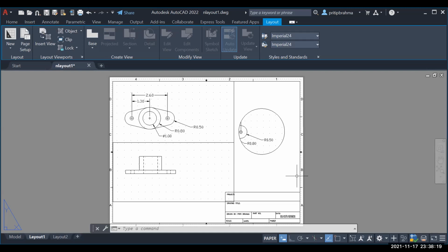So this is how you're going to create your final drawing. And this is a detail drawing. On top of this, you would need your final assembly. So how this piece fits with the other pieces. And let me think about that in the context of your projects. So if you've drawn your isometric, I would recommend making a copy of it and moving all the pieces apart. And that should become your assembly drawing, showing all those pieces coming together.